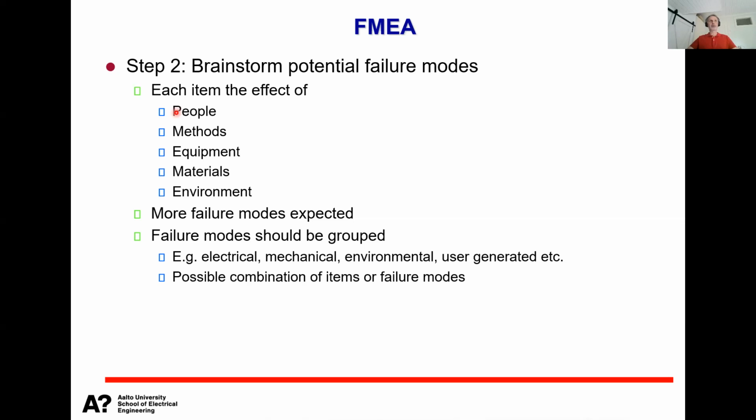So somebody had put their thumb on top of that hole and already put there some grease and maybe some ionic contamination, which then migrates during usage to the actual membrane and starts causing problems. The resonance frequency is changed because the mass is changed or something like that.